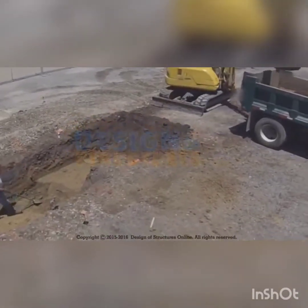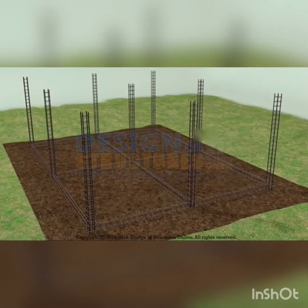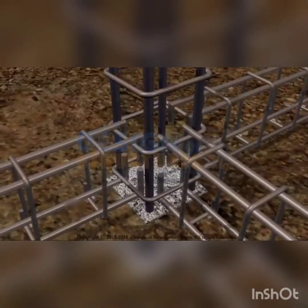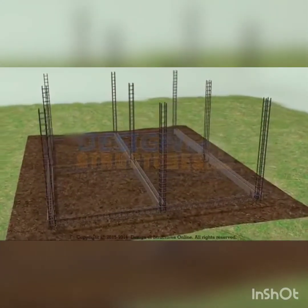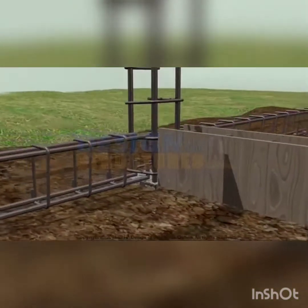Plinth beam above foundation. Beam reinforcement shall be as per drawings. Top bars, bottom bars and stirrups to be placed with proper development length. Joints in the beam shuttering should be tight against leakage of cement grout. Construction of shuttering should permit removal of various parts in desired sequences without damage to the concrete.